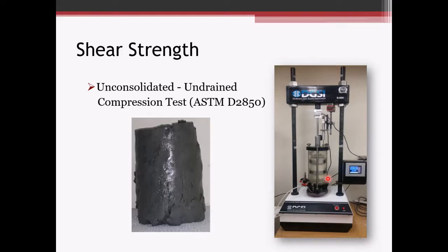The main purpose of this test is to determine the undrained shear strength for short-term loading situations where loads on a soil will happen relatively quickly, where the pore pressures are not able to dissipate. These can be run on Shelby Tube samples. Again, the engineer needs to provide the criteria if it's going to be a remold, as well as the confining pressures to run the test.